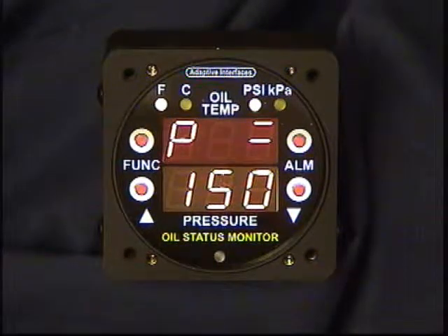Again, to set temperature and pressure with this instrument using different types of sensors, you simply need to know 2 different data points of the sensor. If it's a temp sensor, you need to know the data point for 2 different temperatures, and same thing for a pressure sensor. As long as you can find 2 data points for the pressure, you'll be able to set the instrument. It sets up a linear curve and it calculates the pressure from the sensor based on that curve.